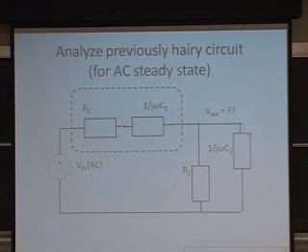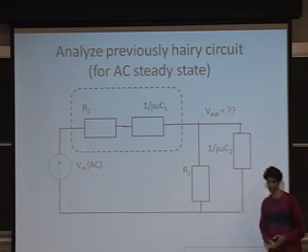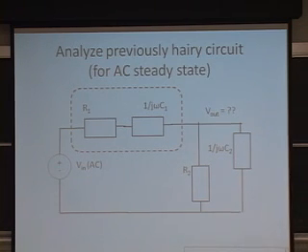So now we've translated these resistors and capacitors into impedances. I've drawn boxes here because now we're dealing with complex valued boxes of impedances. You can still draw the resistors and capacitors if you want, but the thing is now we're generalizing. We're abstracting away from the physical basis of these values. We've shown how resistors are R, capacitors are 1 over j omega C, and inductors are j omega L, so we're cool with that now, and we're going to just abstract away from that.